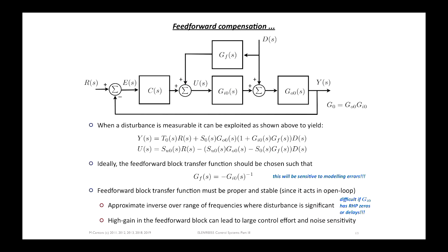If we now look at the transfer function from this disturbance input to the output, you see that the output depends on the disturbance input via this modified transfer function now. And if you can choose this feed forward path to invert this, or make the product here effectively -1, then you get 1 minus 1, that'll be 0. And it's like making Y completely insensitive to D.